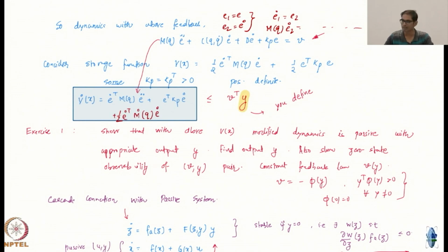Because this is E dot and again a E dot, and then you have an E double dot. And the second order almost linear looking system. Also the term connected to the highest derivative is positive, again a generalization of positive. If you think Routh-Hurwitz criteria, also it's nice, because the coefficient on the highest power should be positive. So that's already something nice that's happening.